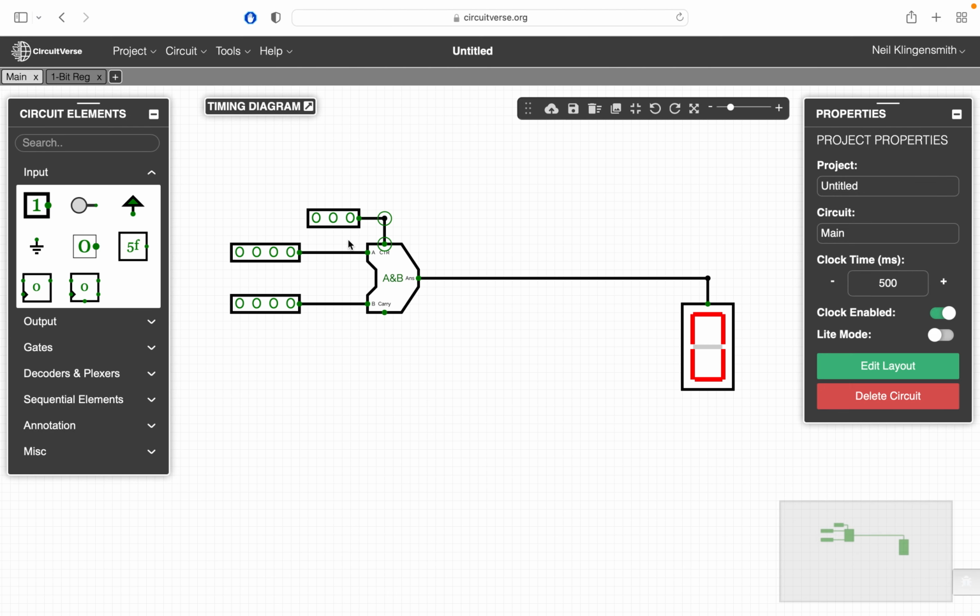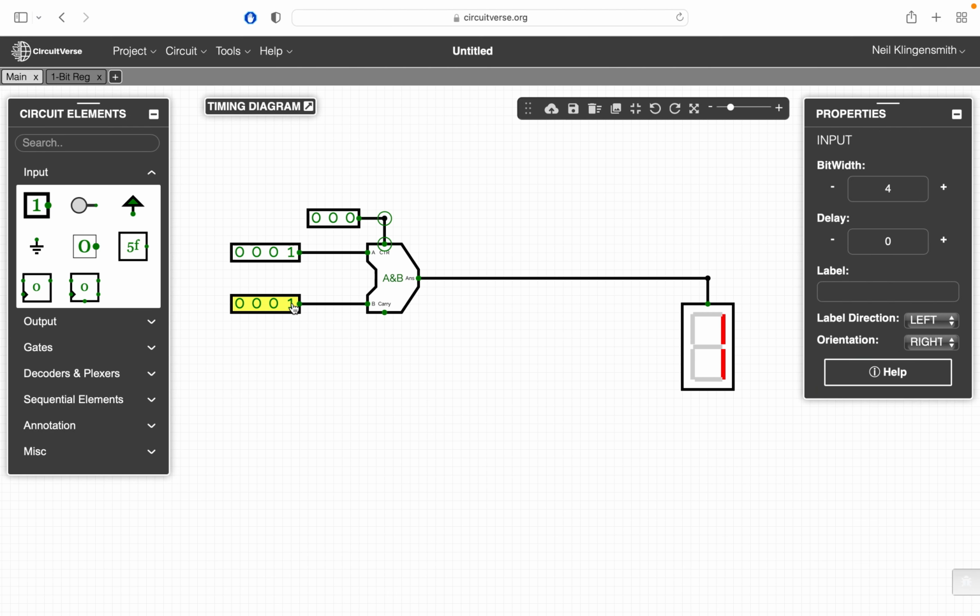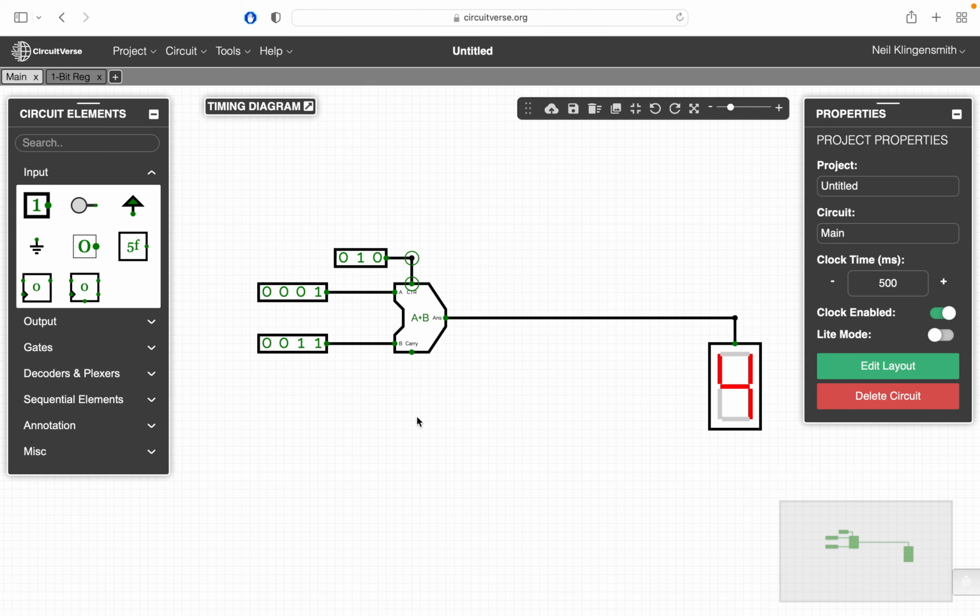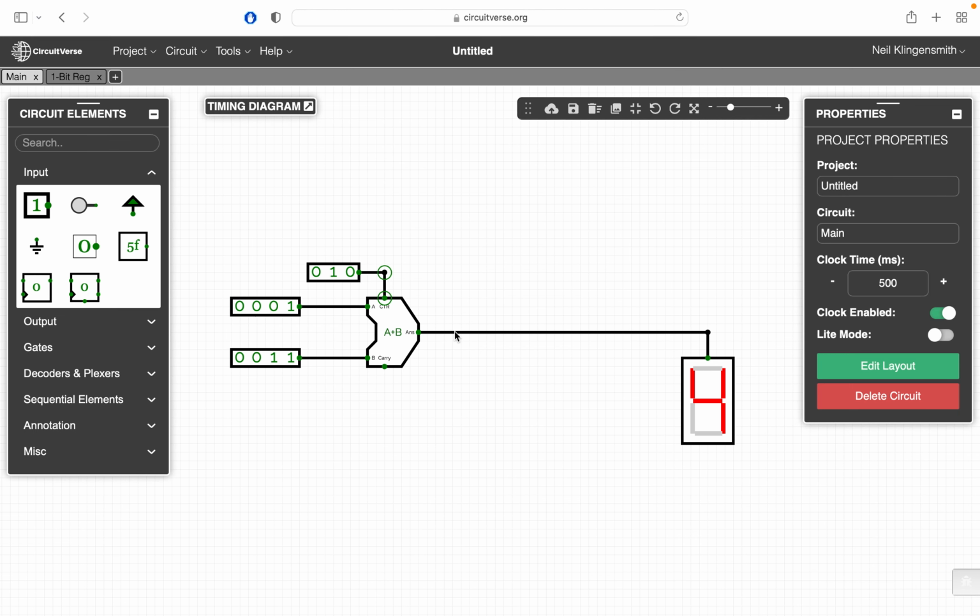Say I wanted to add, let's see here, this is an AND operation, right? So we're ANDing the two numbers together. If I wanted to add the two numbers together, I give it an operation code of 0, 1, 0, and that's going to cause the ALU to calculate A plus B. This is called an arithmetic and logic unit, so it does arithmetic like add and subtract, but it also does logic. Each one of these wires represents a 4-bit bus.